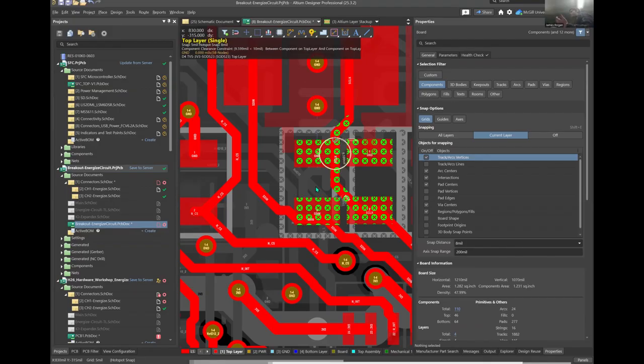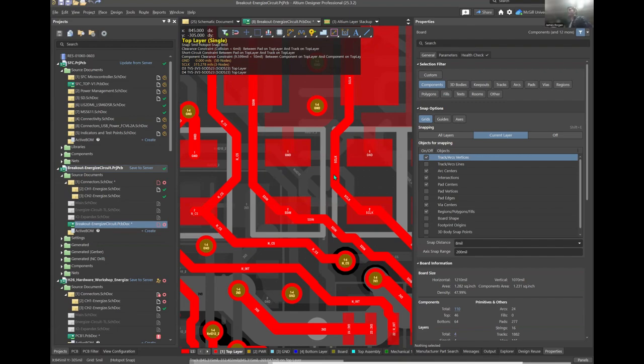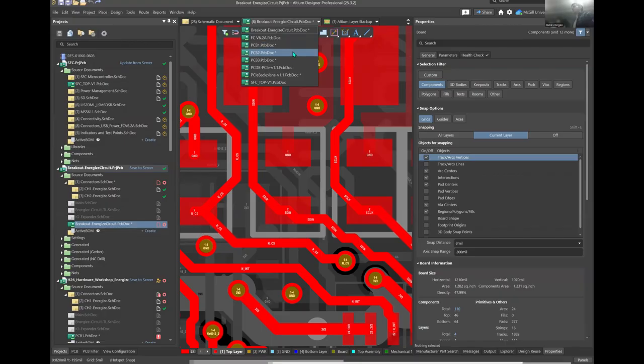Altium basically tells me, okay, there's a violation in the design rules that you told me, where you're not supposed to short these two traces, and yet you are, and these components are too close together. And so it's going to tell me with these green X's that there's a problem here. And so then it'd be the responsibility of me to fix it. And so this is important to set up.